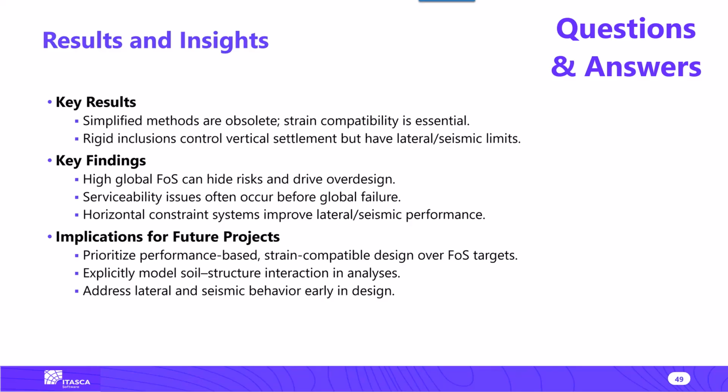Keep in mind that when you're using rigid inclusions, that becomes secondary, because essentially the rigid inclusions are shielding the volumetric deformation from developing in a significant manner. But if you don't have anything, that ratio between the E50 and E oedometer could be in the order of 0.7, 0.75, all the way up to 1, or even a little bit higher for sands. That is a general guideline, but again, it depends on the site.